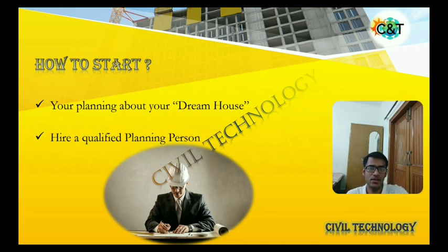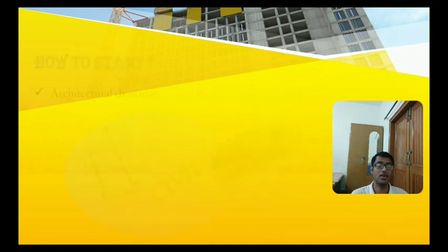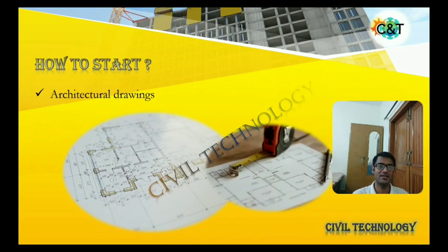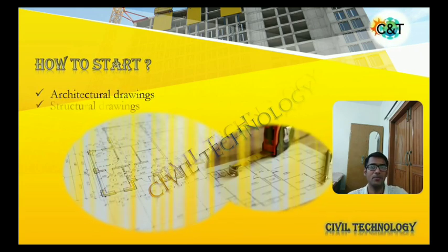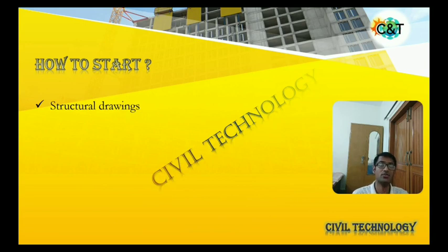The house related drawings are prepared, but you cannot start work now, correct? Because before starting the work you have to get this drawing approved by the concerned authority, whatever the government authority is that deals with the land records. Okay, whatever government authority your land comes under, you have to contact them and submit all your drawings, like all your working drawings and your structure drawings.